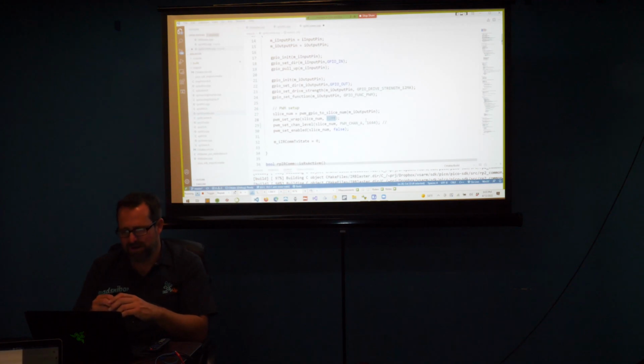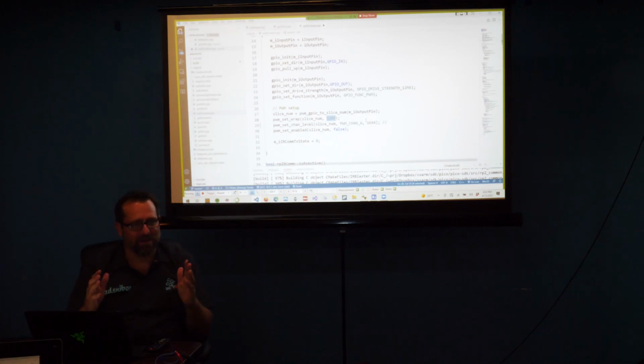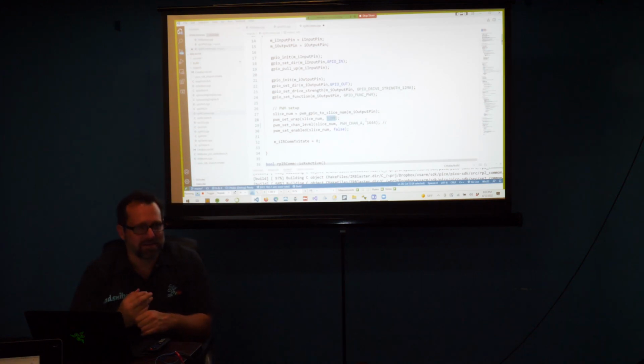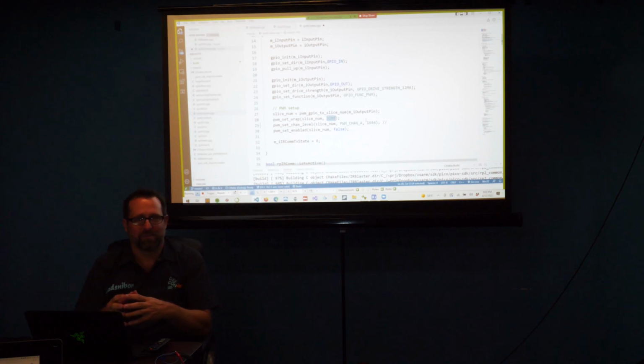To find out what 38 kilohertz is, you figure out the period, 1 over 38 kilohertz, which someone said is 26 microseconds. So you divide that by 8 nanoseconds.